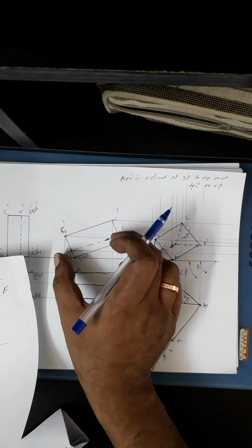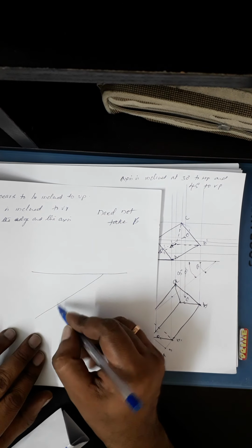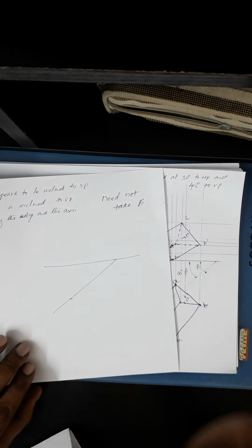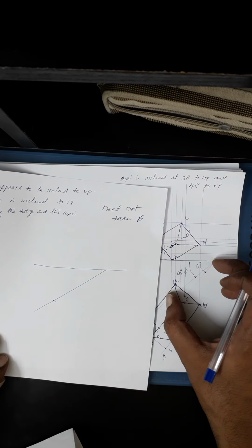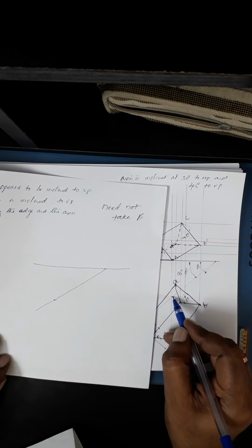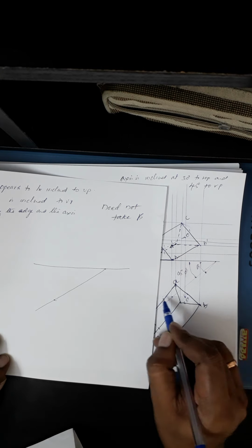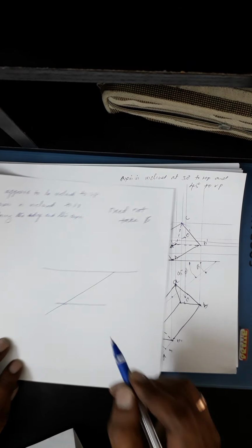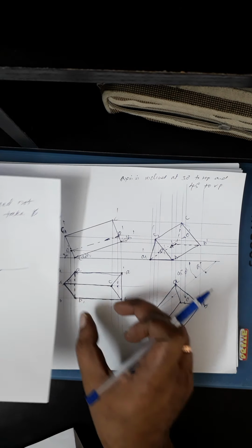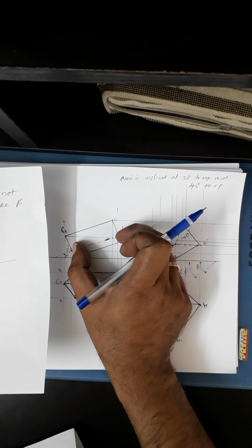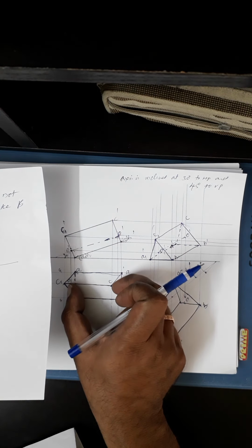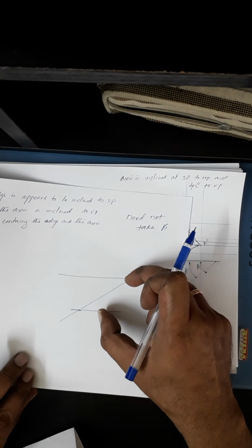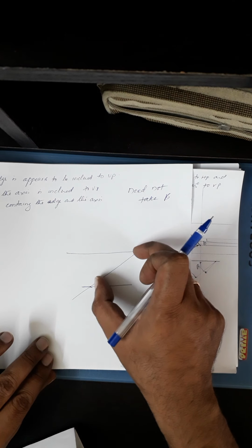On that, you take the true length of the line. If it is 70 mm, you take that 70 mm from this point, with one endpoint on the XY line. So this is the true length of the line. At the true length endpoint, you draw a locus parallel to the XY line. Then if you take this apparent length, which will be less than this length, this is bigger whereas this projected length becomes shorter. So taking that one point fixed here, if I cut on that locus, this length will be less than this, right? Okay.